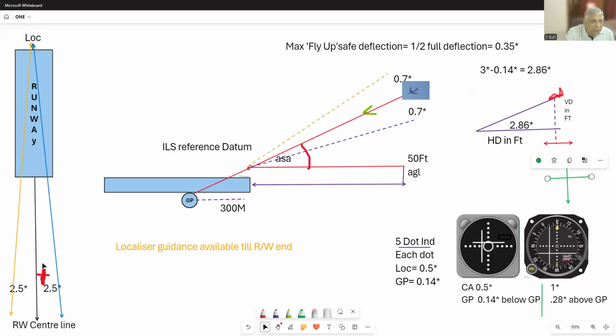Here, I've told you the numericals are: find out the closing angle from this vertical needle where it has gone. If the needle goes to left, you are to the right. If the needle goes to right, then you are to the left. And with the closing angle, they would possibly ask you what is your horizontal distance, which will be rather distance of drag, which will be the distance away from the center line. If this is given to you, then he can ask you distance to go, etc. Application of the 1 in 60 rule. And we had done quite a few questions on that.